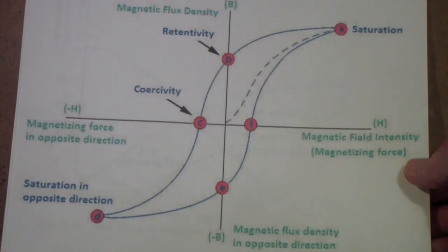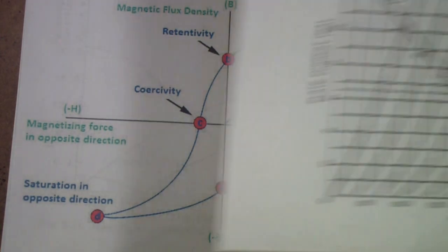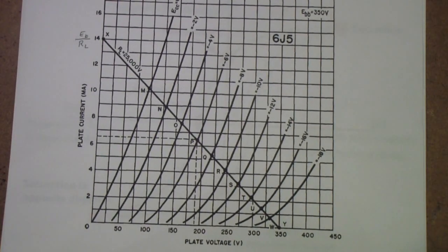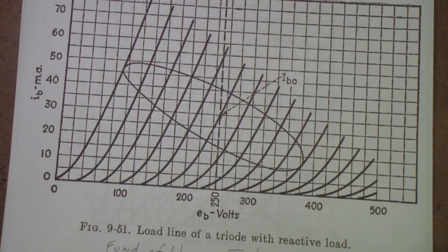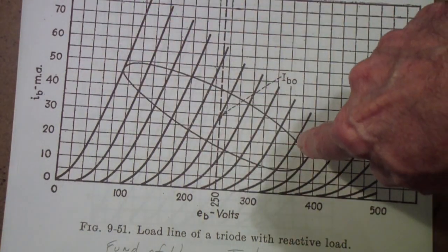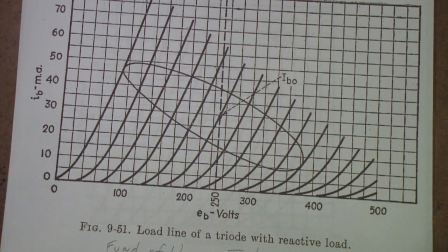And we discovered that because of hysteresis and other nonlinearities in the transformers, you don't get a straight load line. Instead what you get is a parabola. In other words, the tube operates around this path, not straight up and down like a resistor.